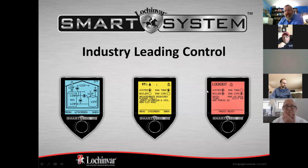And I want to take just a second because people sometimes miss this. We look at our lockout screen, you see a Lockout 1, and we'll talk about space heat demands in a little bit because there are 3. That lets you know that you have a space heat demand, the boiler's locked out, but go down here, that'll tell you what the lockout actually is. It'll always be printed up on the screen and when it happened, the date and time. So setting the date and time in the boiler does become important so you can see that information.